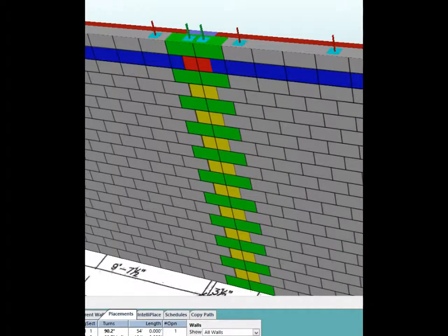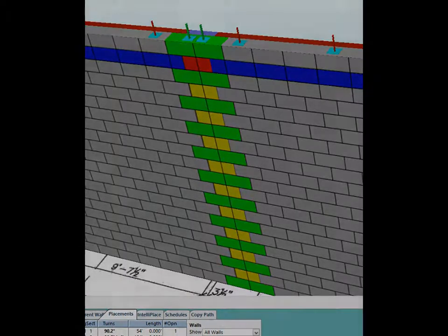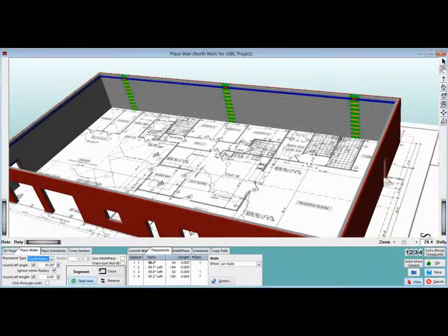Reposition your building so that you can see the inside of the wall project. The control joints will be represented on the inside with alternating halves and holes of the CMU. Look closely, and the special material you put in the bond beam band will be present as well. The rebar and grout will also be present at the top of the wall. The control joint placement has now removed all of your standard material quantities and replaced them with the special pieces associated with the control joint and the bond beam band.